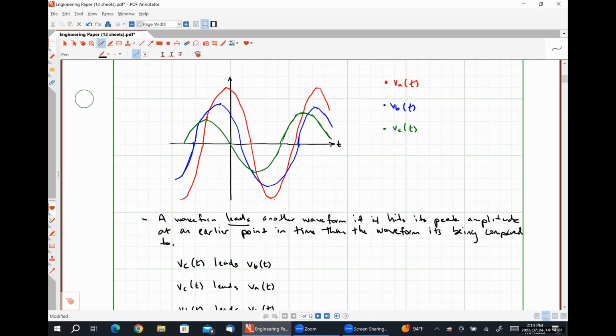Now, I personally often struggle with looking at these time domain graphs, where all of the signals are plotted as a function of time. They look a bit busy to me, and as I mentioned in our last class meeting, it can be confusing to realize that points to the left of the vertical axis mean we are at an earlier point in time with positive phase angles, and points to the right mean we are at later points in time, with negative phase angles. So there is another method called a phase diagram that I personally prefer to use to determine leading or lagging. Okay.